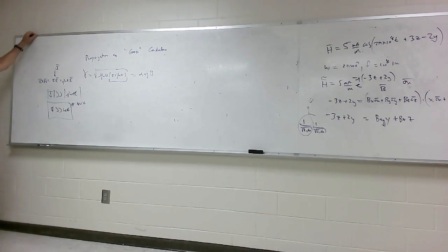Can y'all follow me? Sigma is greater than omega epsilon. Omega epsilon is the coefficient of E, and this is called displacement current. Do you remember this class, displacement current density? That's displacement current density, and that's conduction current density.